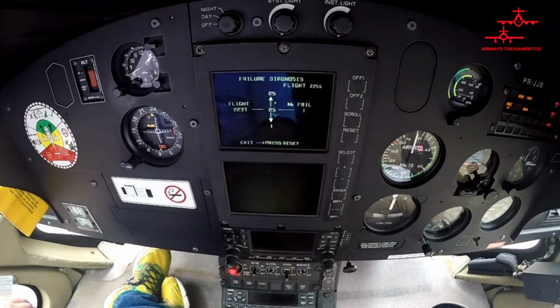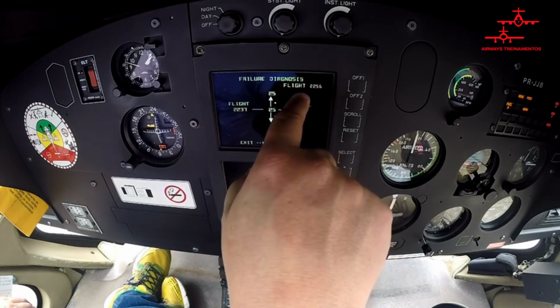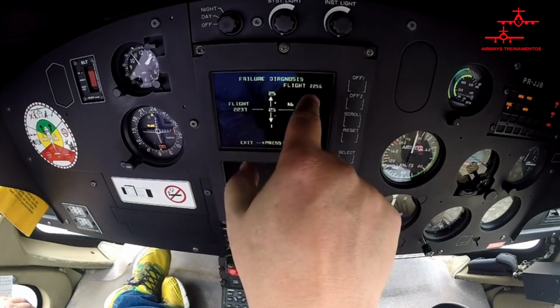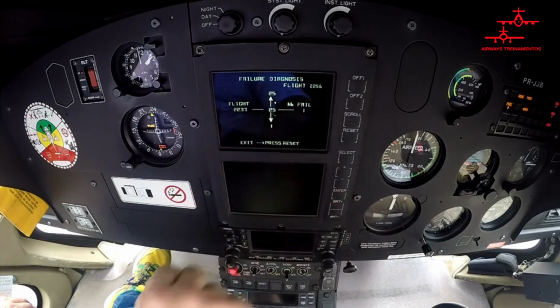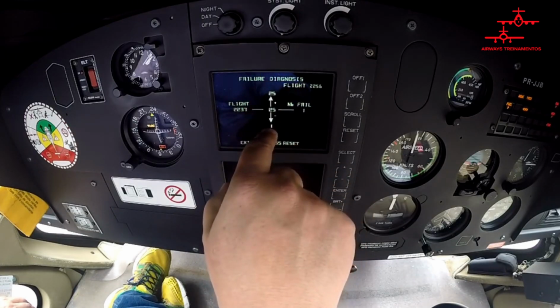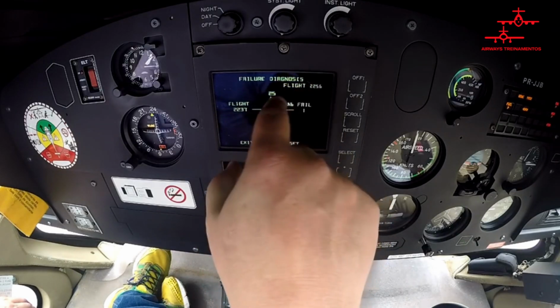I press enter, and here's where a lot of people get confused and don't understand this screen, right? So, let me explain. Up here in the upper corner, it shows the total number of accumulated flights for the aircraft. So this aircraft has completed, since this VMD was installed, 2,256 flights. And then out of these 2,256 flights, I have this cross here. So what does this vertical number above and below mean? This will always be 1, and the number on top will tell you how many flights had faults. So there were a total of 25 flights with faults.